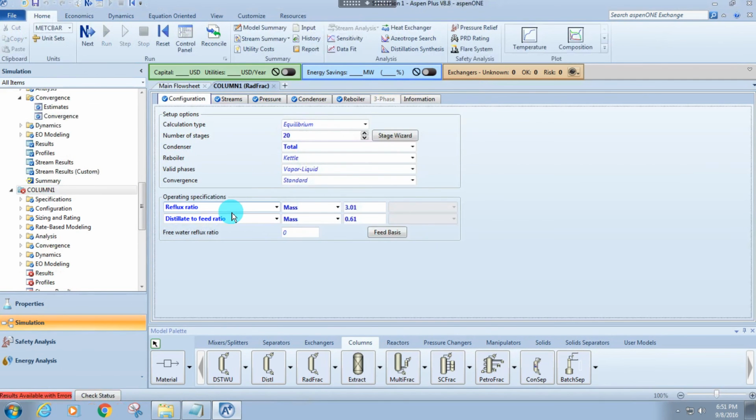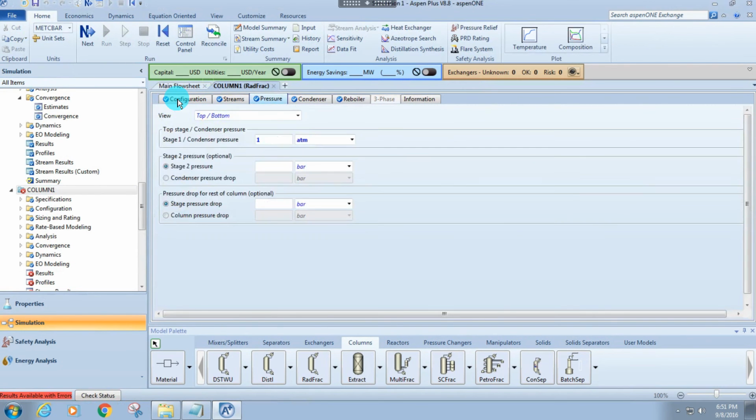The other thing is sometimes it's weird because VLab Aspen will be a little bit different than on the computers downstairs. I trust the computers a little bit more. It's still the same thing, but we've just found some unexplainable troubles. If you notice what I did, with each specification, I changed it by very, very little. It's just how the first guess of the first iteration interacts with just the next run. It's just trial and error. Sometimes it will give you an error, although it really is feasible, and you just have to be patient.